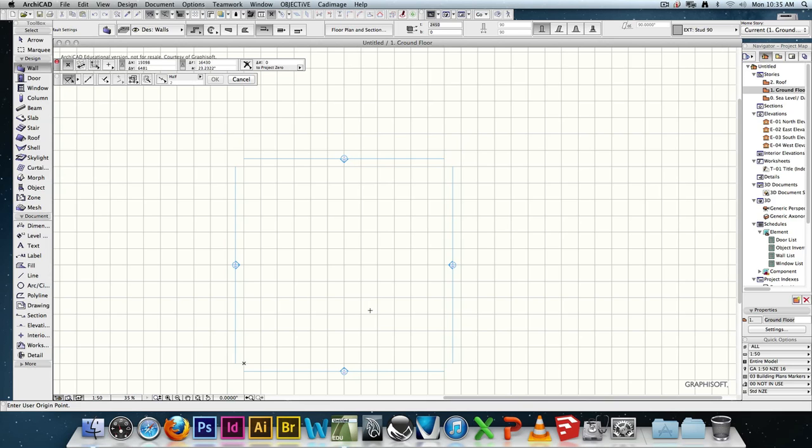However, we can move this point whenever we like. So if you decided that actually I now want the origin to be somewhere else, I want it to be on the corner of the building, because I've got a whole bunch of measurements that all radiate out from that one point, you can actually move that point just by using this guy, and you just click somewhere. And so now all of my points, see all the values here are all originating from there.